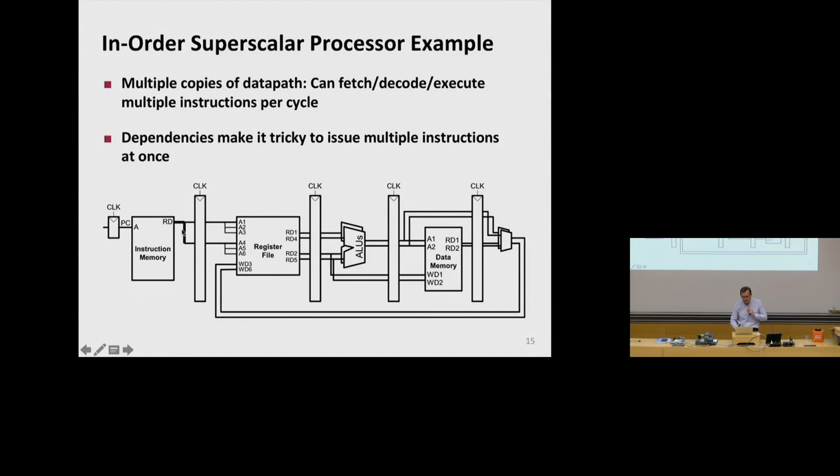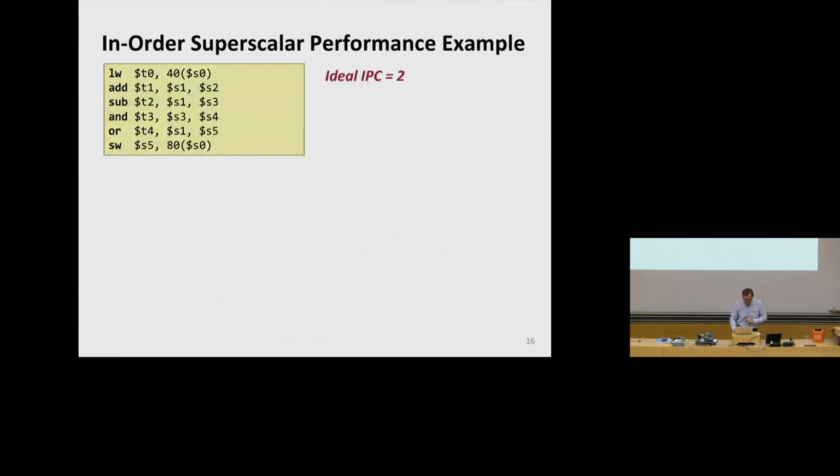No, basically what this is doing is that it's fetching 2 instructions and assuming that they're consecutive. But yes, if you really want to be able to fetch, so this goes into the branch prediction problem that we will see. If you really want to be able to fetch different locations that are not sequential, then you really need 2 ports. And people play a lot of tricks over there, which we're not going to get into. But that's a very good point. But we're exploiting the fact that instructions are sequential in this case.